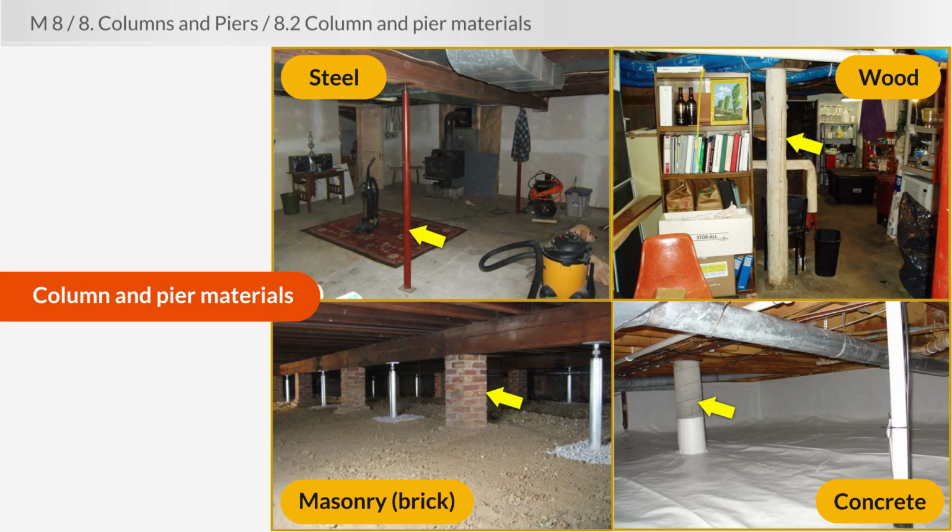You could dig around in the stone a little bit around the screw jacks and see if there's any type of foundation that's been poured, any type of footing. But even regardless of that, you'll certainly want to mention on the report that it looks like some structural modifications have been made, to give your client a chance to check with the current owner. But really, it looks like whoever did that did a very nice job.